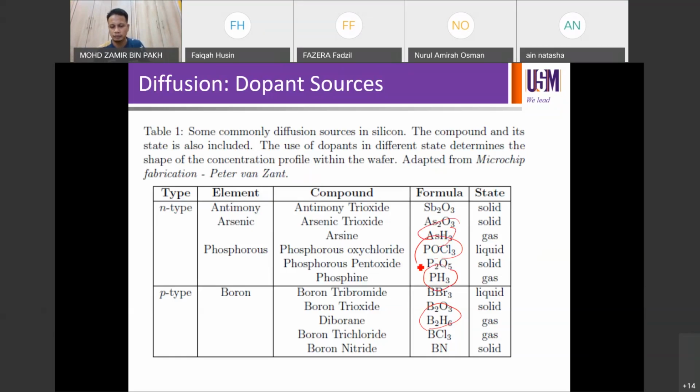If you look at solar cell, if you have a P-type silicon wafer, you want to do N-type diffuse layer, they normally use POCl for N-type emitter, a very thin one, like about 100 to 200 nanometer thick for solar cell.